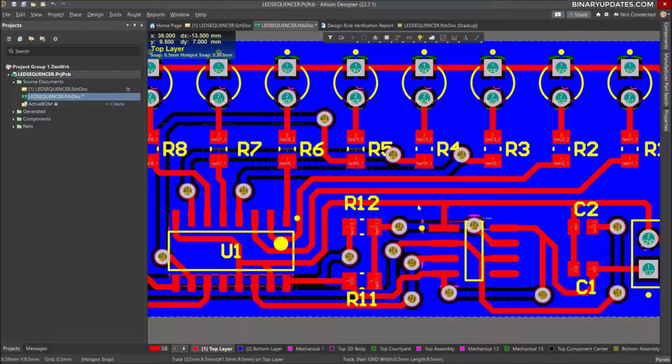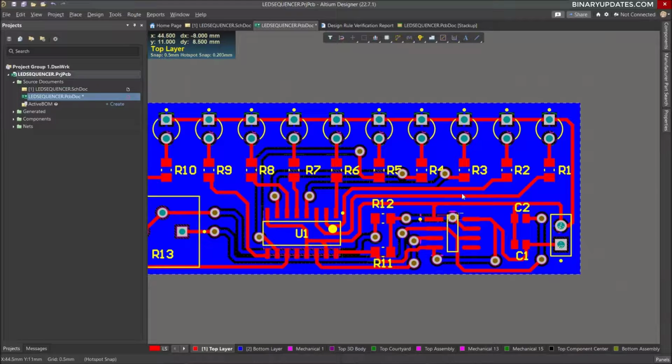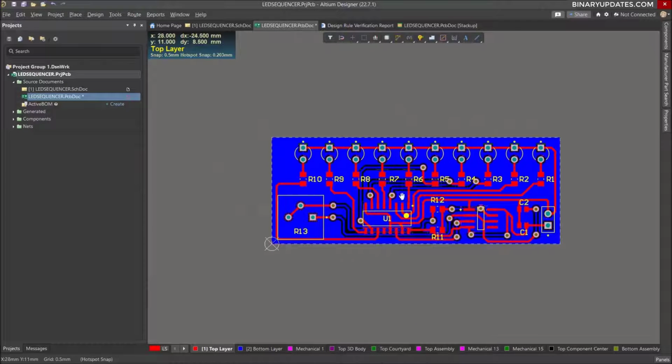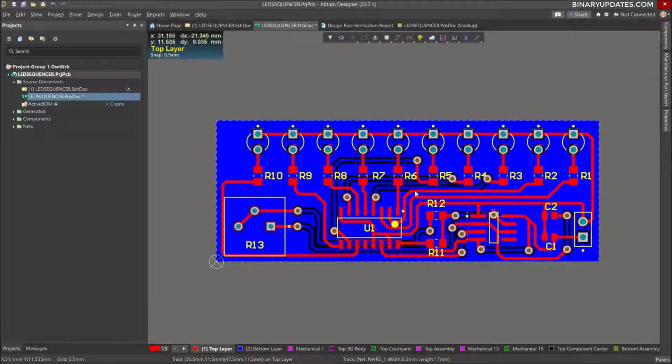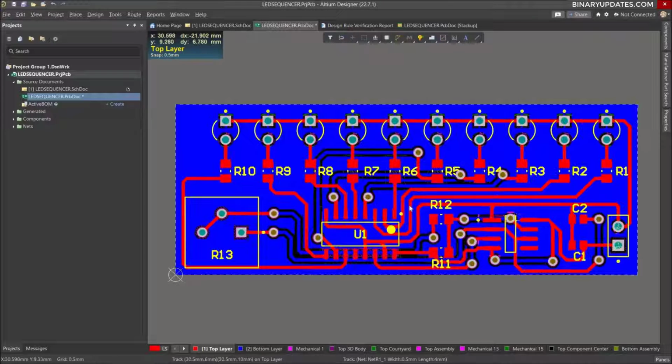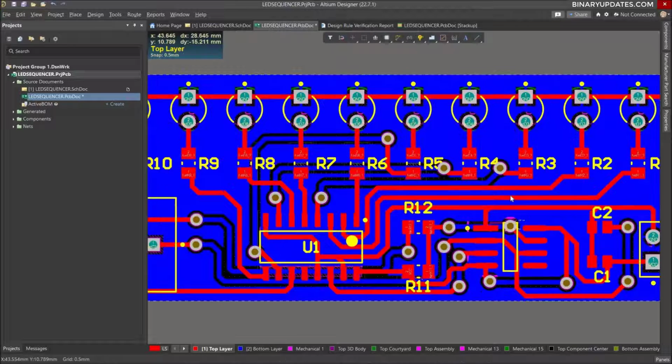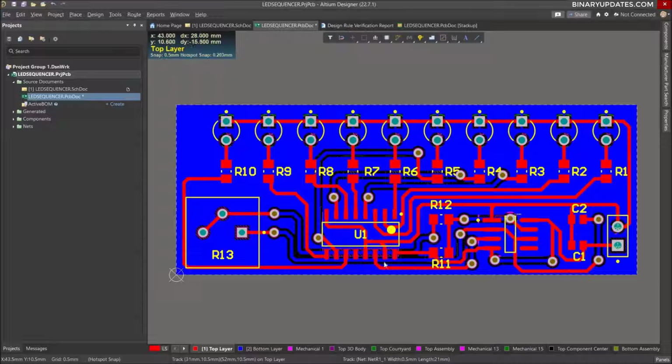You can either put it like this, or you can check on the schematic what is the value of a particular resistor or something like that. But now our PCB is ready. If you want to give some name, you can also put some text on the board. Rather avoid this for now. I just want to make it very clean, neat and simple, to the point and focused. So this PCB is basically ready to generate the output files, that means Gerber files.